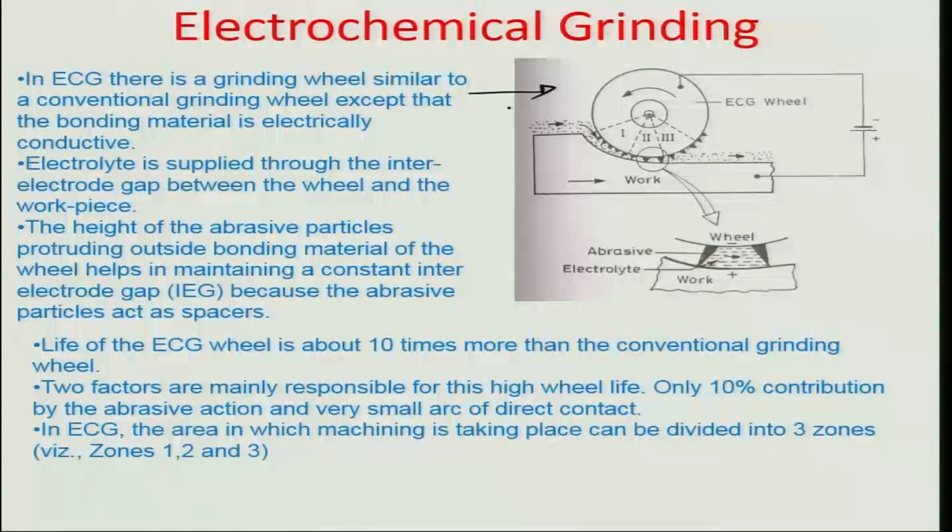You have a grinding wheel, as you can see, which is more or less similar to the conventional grinding wheel, except that in this case the material which bonds these grains which are sticking out of the grinding wheel is conducting in nature. Okay, so I can say that the bonding of the abrasive grain is electrically conducting.